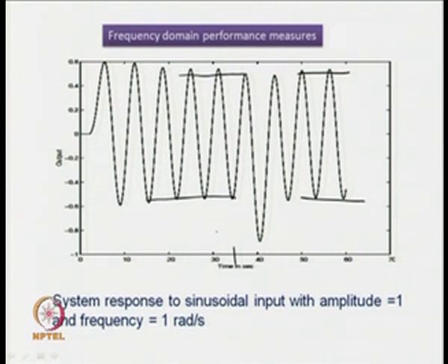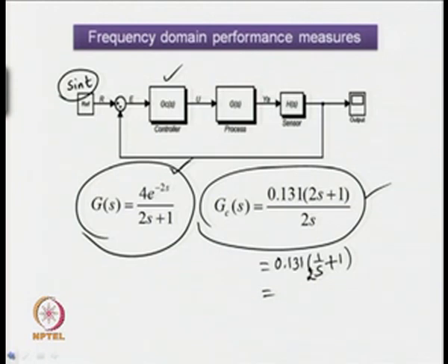Apart from this information that the system output is stable for sinusoidal input to the system, it is very difficult to make out any other quantitative performance measures from this output. It is difficult to visualize the effects or good effects of a properly designed controller from this output. Therefore, we need to consider the loop gain of the closed loop system for frequency response analysis of the system.